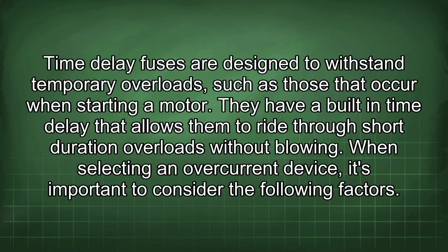Time delay fuses are designed to withstand temporary overloads such as those that occur when starting a motor. They have a built-in time delay that allows them to ride through short duration overloads without blowing.